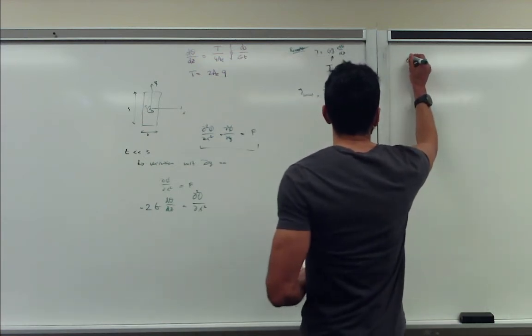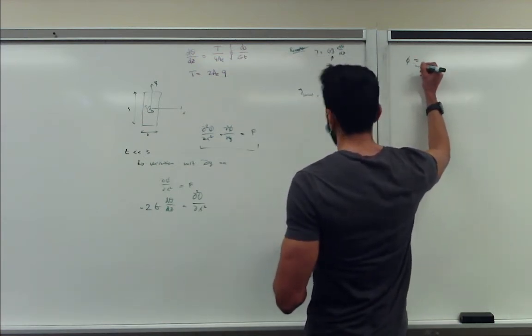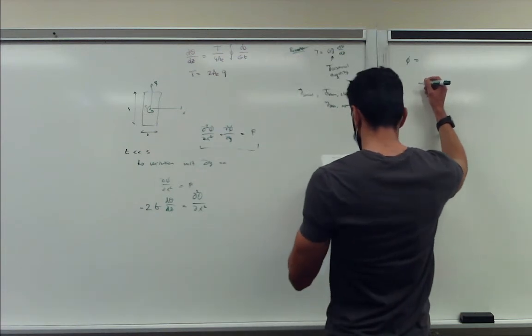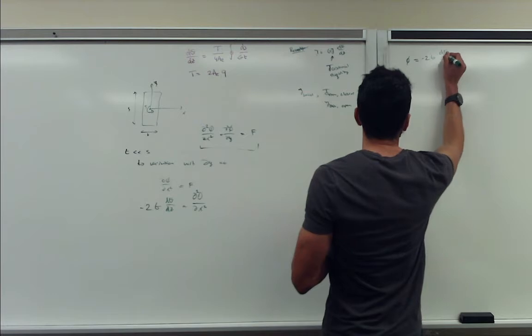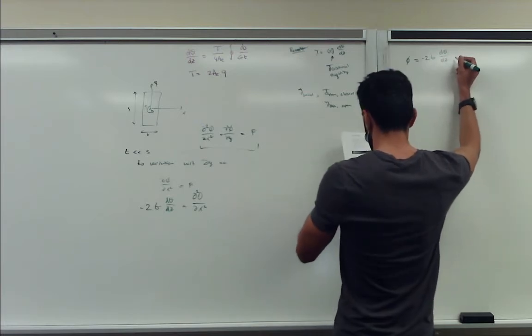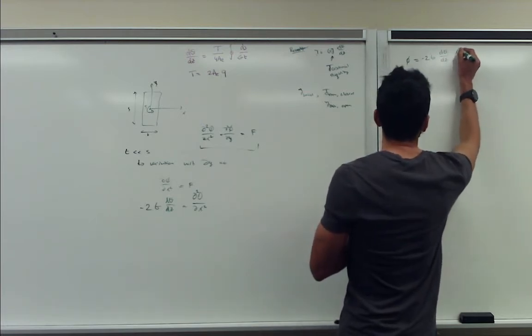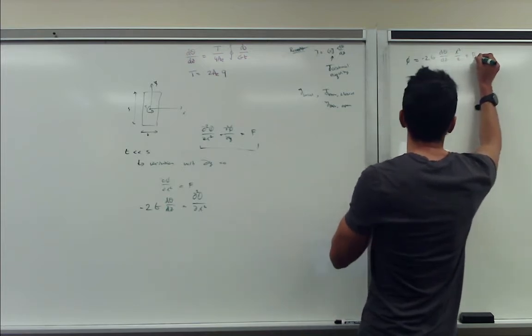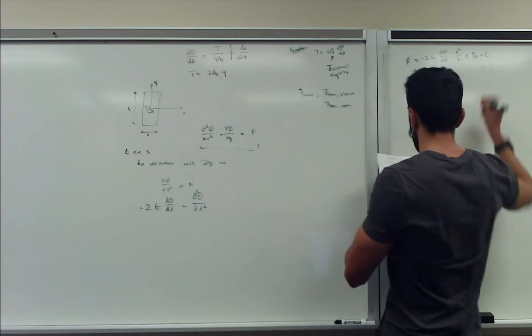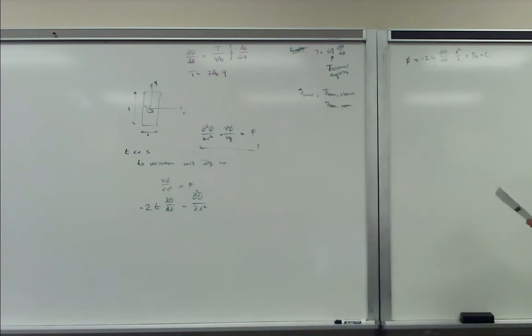So our stress function now becomes, integrating this twice, G d theta dz times x squared over 2 plus bx plus c, where b and c are our integration constants.